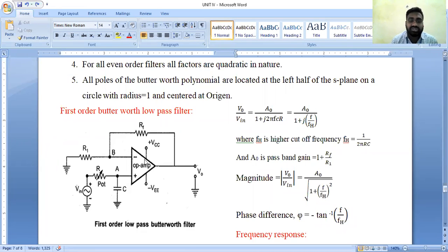See here, so this is our operational amplifier, a 5-terminal device. Two are input terminals. One is the inverting terminal, the negative terminal. Try to recall the knowledge we discussed there. Operational amplifier is having 5 terminals. Two are input terminals. The negative terminal is the inverting terminal, and the positive terminal is the non-inverting terminal. And plus VCC and minus VEE are DC biasing voltage terminals. And this is the output voltage terminal.